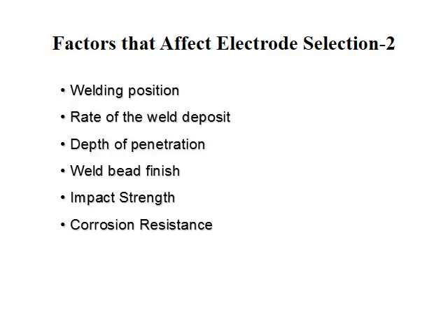Impact strength definitely comes into play, especially in industries such as oil and gas or mining, and especially in locations where the environment's going to play a role and you're going to have very cold temperatures. A lot of steels don't react well to really cold temperatures. Well, most don't. It just depends on what the material is. So impact strength: you need to see how much impact energy this material can absorb before it breaks.